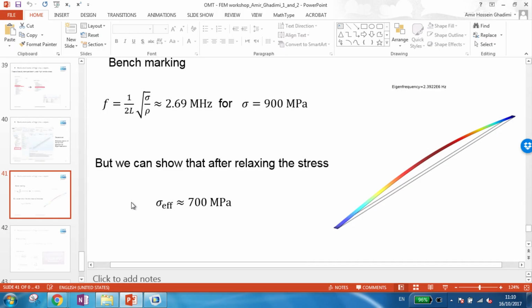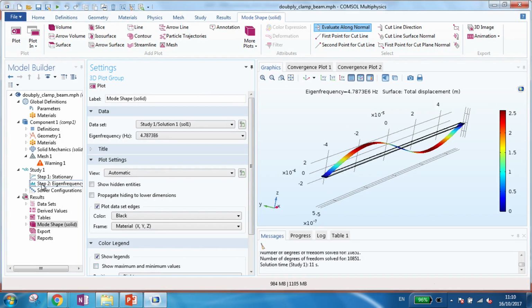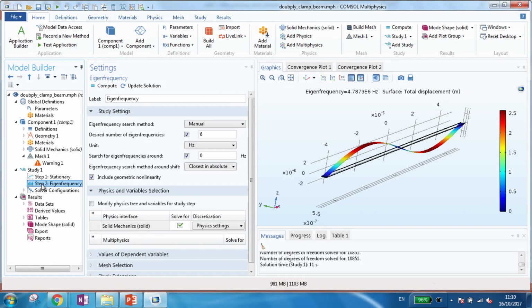Well, for doing that, you can just come to the same simulation and just disable the eigenmode solver, because it automatically throws away the results of the first one. So just disable the eigenmode solver and then say delete configurations, this solver configuration, because it's in the memory that it needs to do the eigenmode solver.